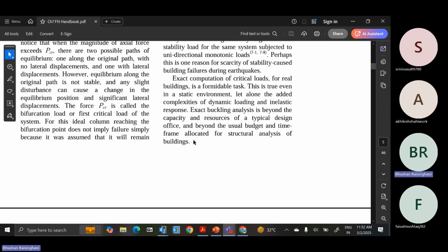So in the dearth of time and resources, we are not able to exactly analyze each and every component, and hence we are not able to reach an exact deformation criterion for each building. So in that case, how should we ensure that the minimum criteria is met, for which the code has specified a 0.4% drift limit.